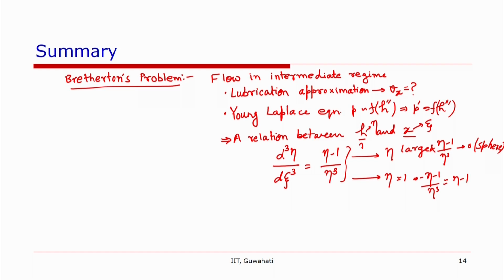Okay, so when it was a sphere, we compared the two principal radii of curvature, because it can be fitted in a sphere and these two curvatures will be equal, and from that we got the radius of the front spherical portion, and from that we could calculate the film thickness.